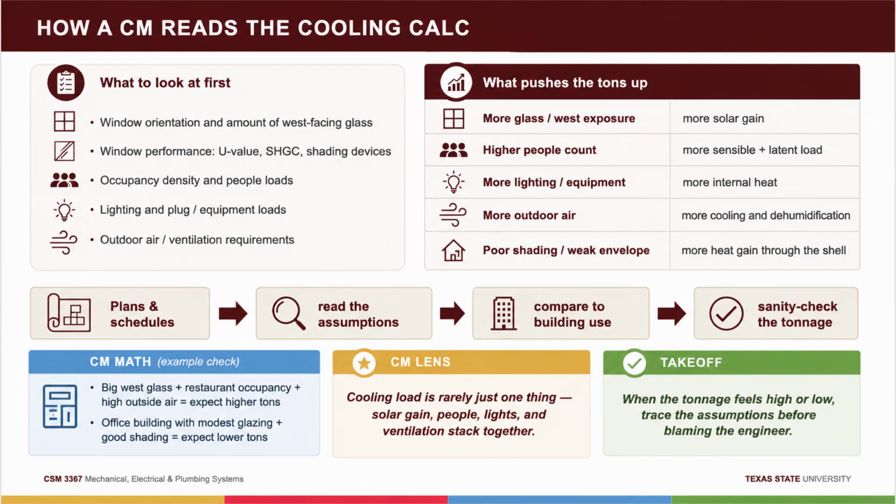And the killer in our climate, it stops dehumidifying. Latent removal, the water pouring out of that condensate line, only happens while air is moving across a cold coil, and the coil needs sustained runtime to get cold and stay cold and keep condensing. An oversized unit satisfies the thermostat so fast the coil barely gets going. Temperature, handled. Moisture, barely touched. Result: 72 degrees and swampy, cold and clammy at the same time.